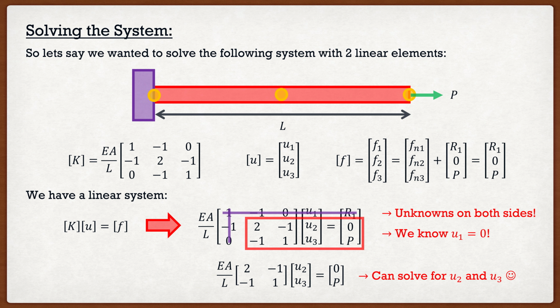But the nicer thing to realize is that now that we know all the nodal displacements, U1, U2, and U3, we can determine our approximation functions, or our displacements within the elements themselves. If I know the approximate displacement function in one of the elements, I can take its derivative to give me the approximate strain distribution. And if I know the material behavior, I can convert that strain distribution into a stress distribution. We're going to talk more about that once we start talking about quadrilateral elements, but that's a different lecture.